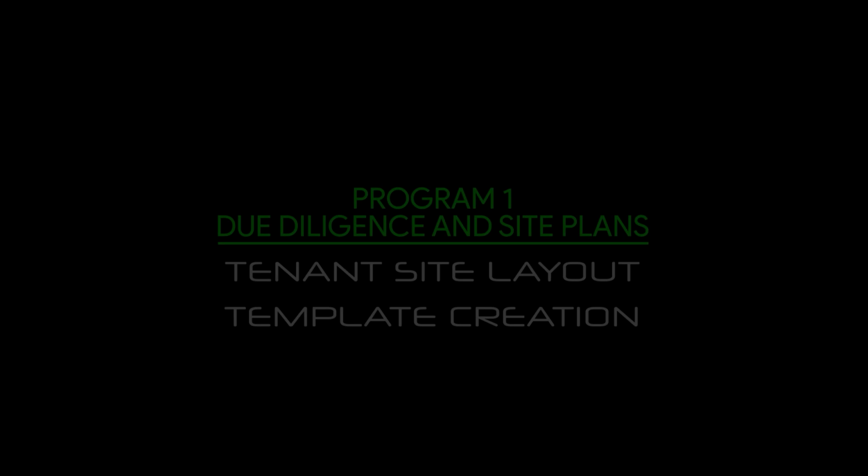So we're using this to kind of know what they want for the shape of their site to be, but it's just an image, so we can't really convert it to a DWG file, and we don't want to just trace it and have it be off and make the dimensions be 24.37 feet. We want everything to be in even 1 foot increments. So today I'm going to show you how we grab an image and the process that I would go through to turn this back into an orthogonal site template that has exact 1 foot incremental dimensions for the site. So let's learn.